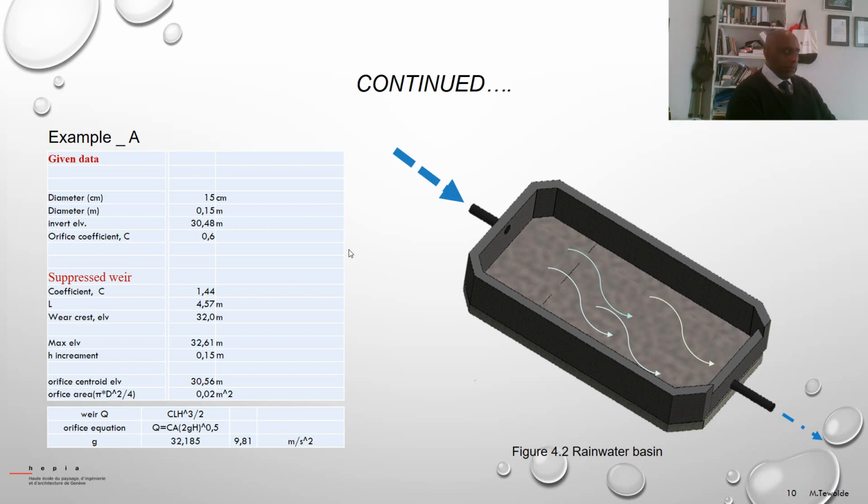Or we may calculate it using rational formulas or other catchment study formulas. For example, the water that is harvested from the catchment needs to be calculated from the SCS curve number method, the methodology where we can calculate the volume of water, the runoff, and also the peak discharge.